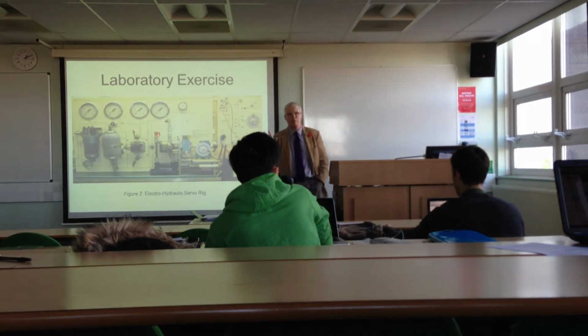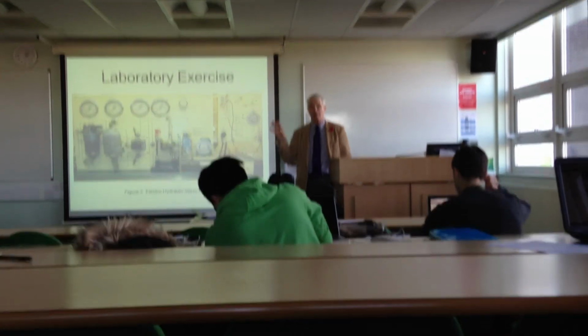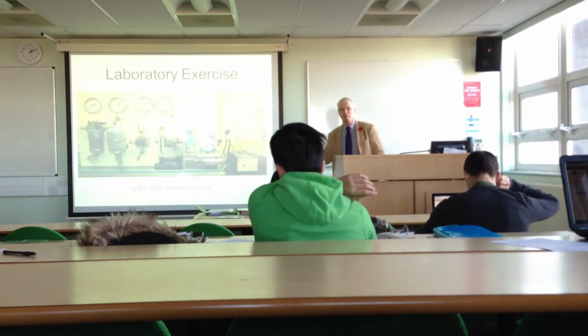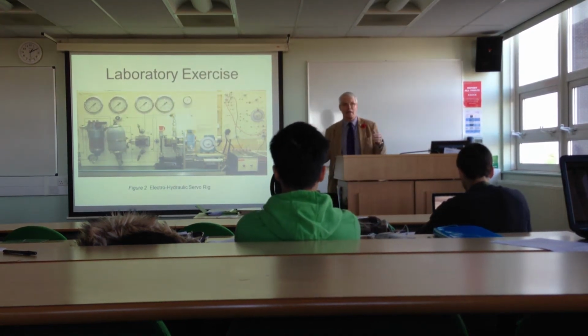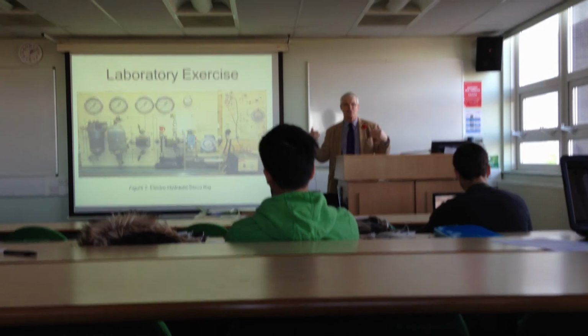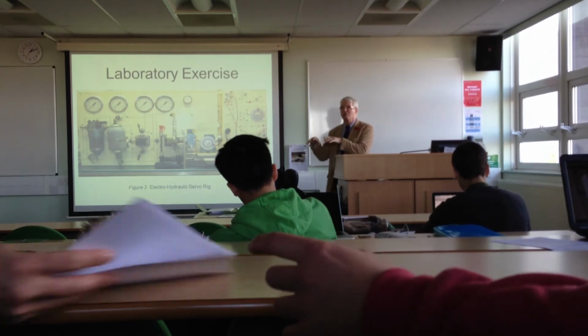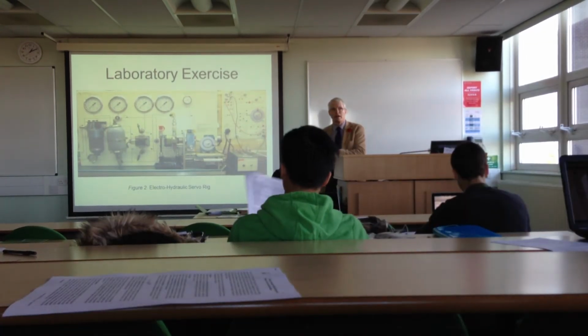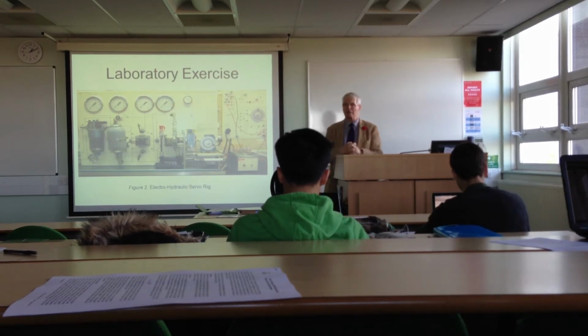So if we had a fly-by-wire system where the output was a hydraulic motor, and if you look at an Airbus, for example, then the slats on the leading edge of the wing, the flaps on the trailing edge, are actually driven by hydraulic motors. They're actually buried in the fuselage, in the center wing box. And there are two hydraulic motors driving into what's called a differential.